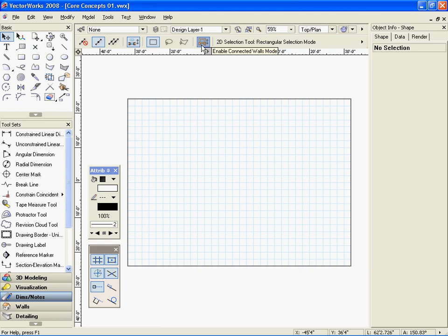This is often a good way to find parts of the drawing that have accidentally been placed far off the page. If objects are selected when the button is clicked, the screen will zoom so the selected objects fill the screen. The Zoom In button doubles the magnification when clicked. Press Alt-click on Windows or Option-click on Mac to zoom out by 1/2. If objects are selected, the zoom will center around them.